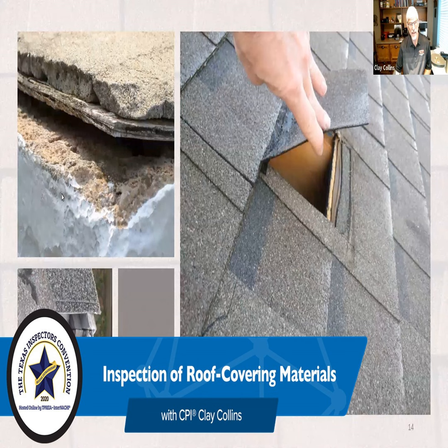So if I put my hand on it and it scorches my hand, I'm concerned about the impact of me walking on that roof. And I would use the hand scorch because it also increases a safety issue. If that roof deck is so hot that you have to keep lifting your hands off, you're going to have a problem getting on and off that roof.